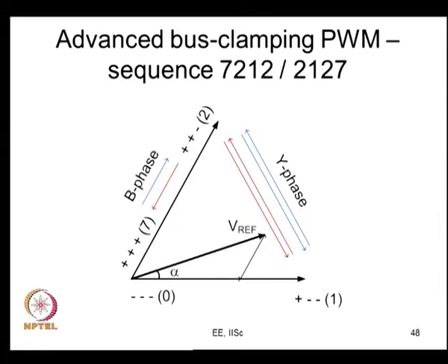So, here again you have this situation where you will see that this is when R phase is not switched. So, when R phase carries a high current or the switching energy loss corresponding to R phase is high, it is better not to switch R phase, and if for example Y phase has got a lower current, this might really be an advantage to do that. That is one way of looking at it.